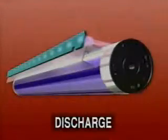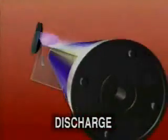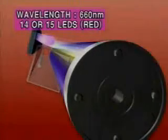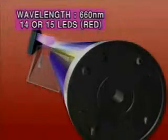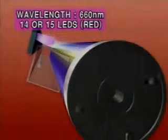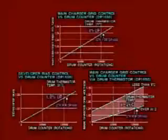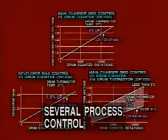Finally, to even out the charge on the drum for the next charging process, the light from the discharge LED array, where 14 or 15 red LEDs with a wavelength of 660 nanometers are arrayed, illuminates the entire drum and discharge is performed. This is the end of the copying process.